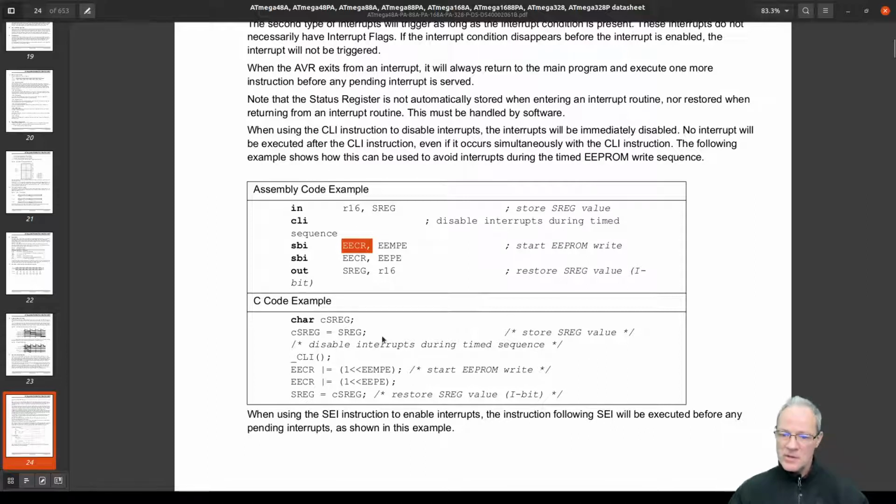Okay. So in this case, what we're looking at is store byte information. That's what I think this instruction was, if I remember. But we also have the out instruction, and the out instruction is writing to SREG, to a certain register, and it's writing the value from the general purpose register to this register.